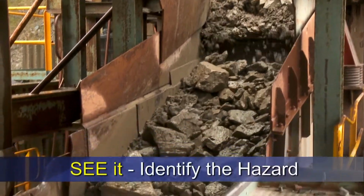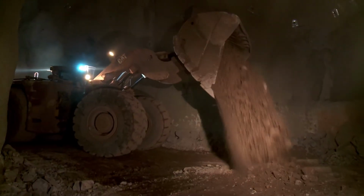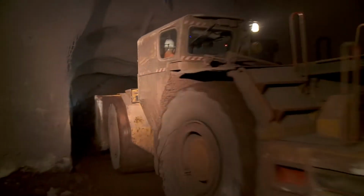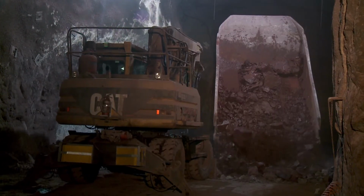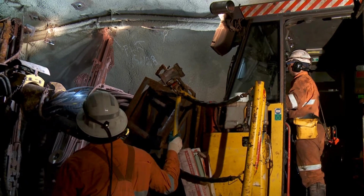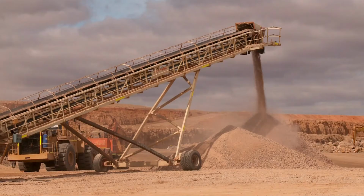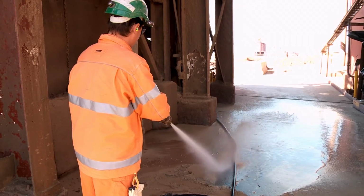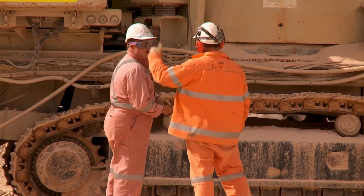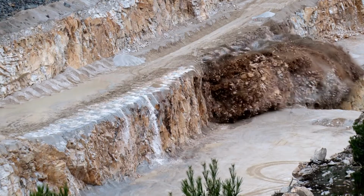See it, identify the hazard. Noise is easily identified because we can hear it most of the time. Noise may damage your hearing and cause other serious health problems such as stress, hypersensitivity to noise, increased blood pressure, and increased heart rate. The main risks with noise are health issues for workers on site and the general public in the vicinity, interference in communication between workers, environmental issues.